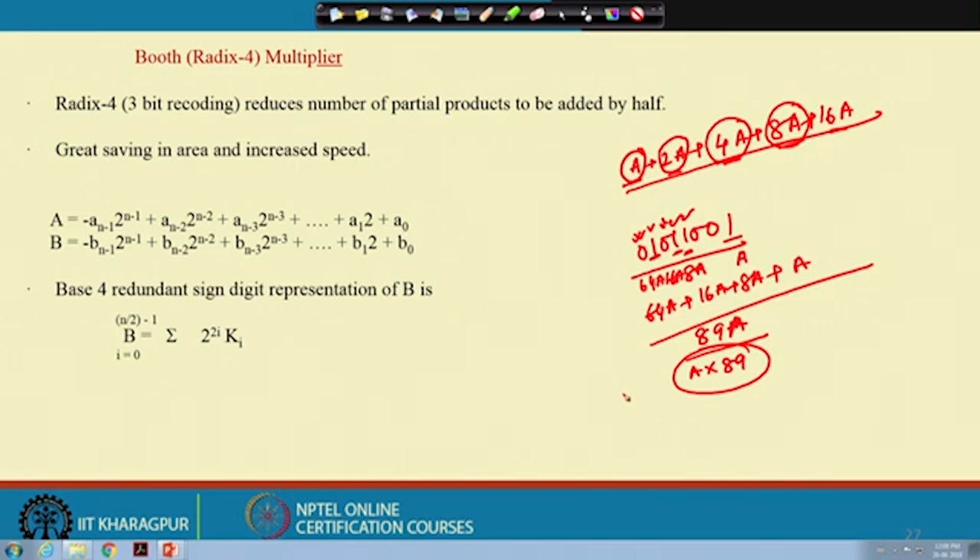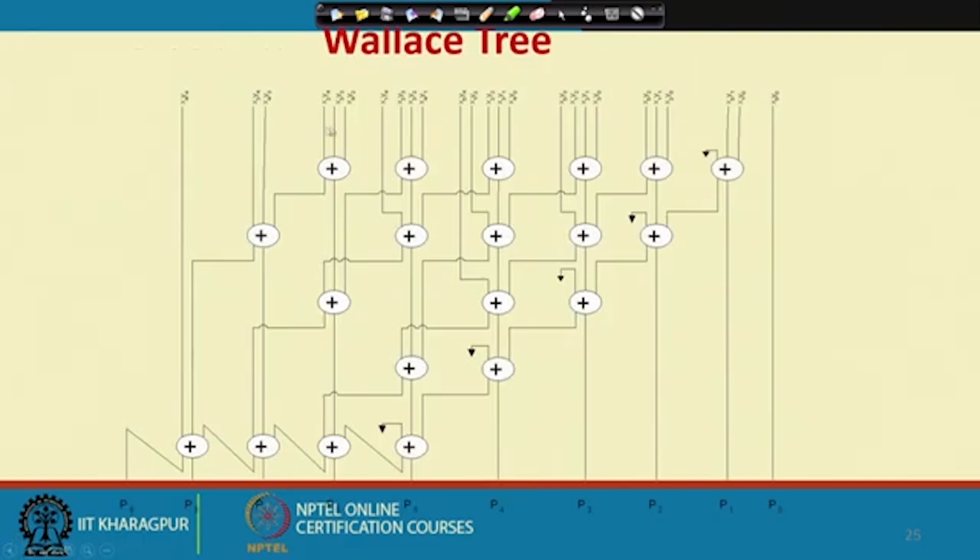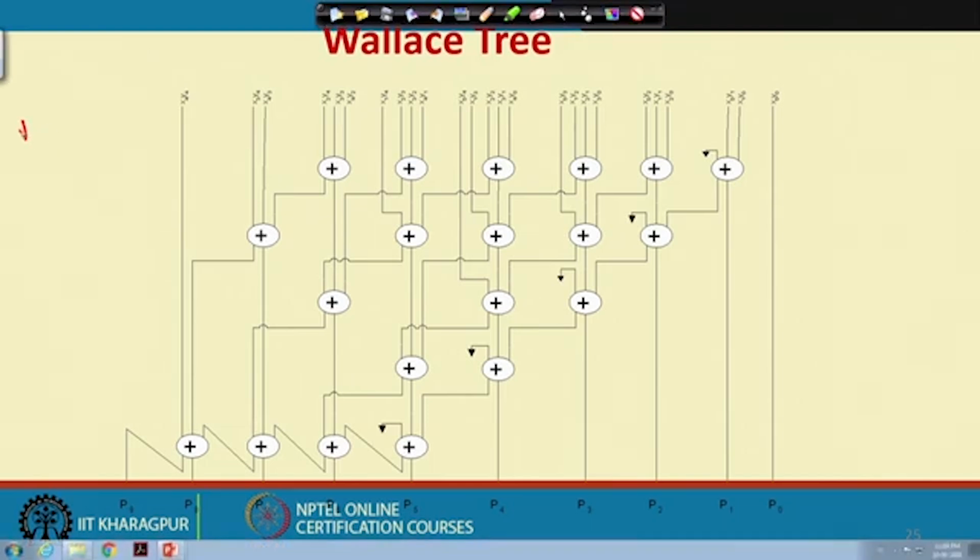But in both the multipliers, what is the problem in this array multiplication? We are considering each of these bit positions. Okay. So, if I go back here, each of these bit positions we are considering to find out the corresponding partial product. So, if I consider x of 8 and y of 8, at that time there are 8 combinations of partial products that I need to generate.